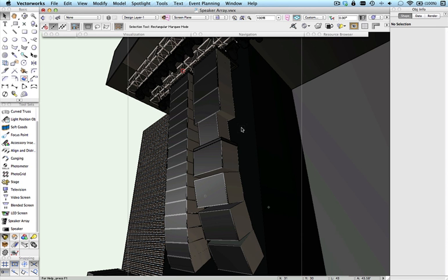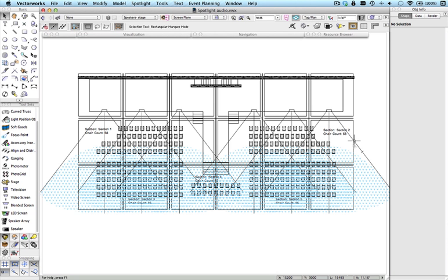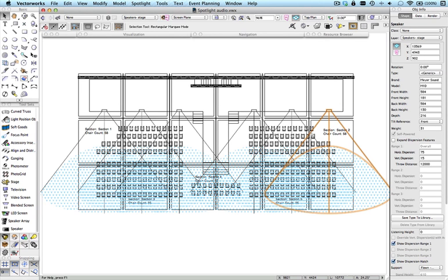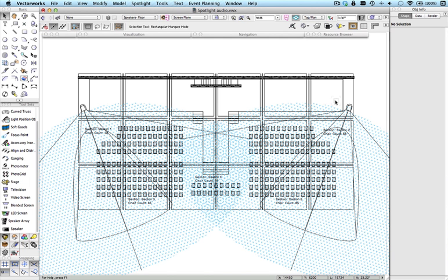And the other thing you can do is to look at the dispersion of the speakers. You will have noticed that there were some dispersion options in those dialogues. If we switch to this file here, you can see that here are a number of individual speakers, and these are actually showing the dispersion. You can see that you can check that option to show the dispersion range and fill it with a hatch or not. So just looking at a couple of different ones there.